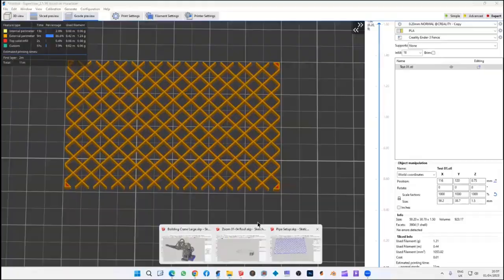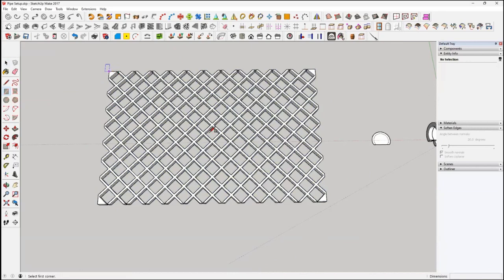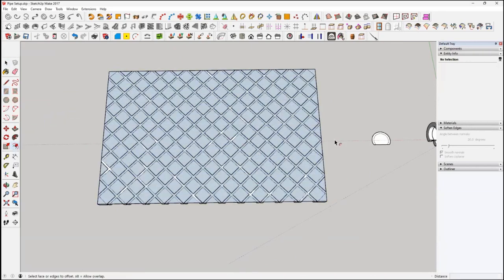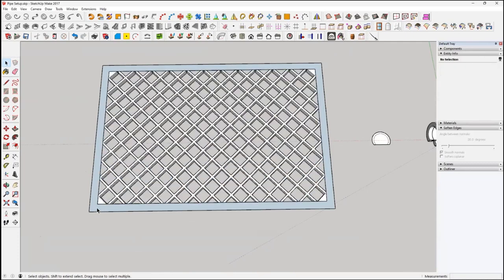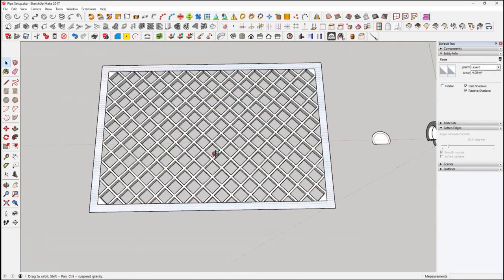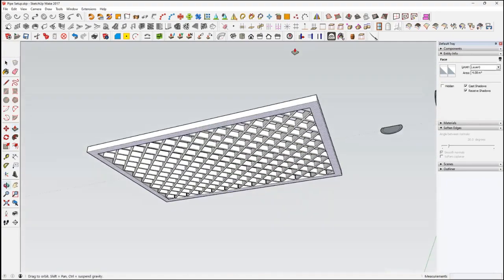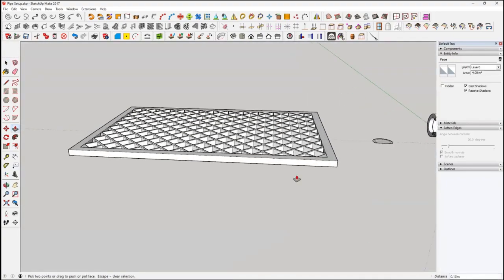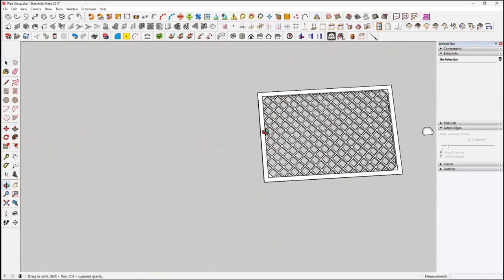Now, really, if you're going to do that, you want to put an offsetter. You can do it now, actually. Put a square offset the edge, so 0.2. And delete the grill. Reverse that face, and then you can push. I mean, we could have done this on the original one, I didn't. And you just put it down and reference on the front. You know, you got a nice grill. And you can do it any size you want. This is the good thing about it.